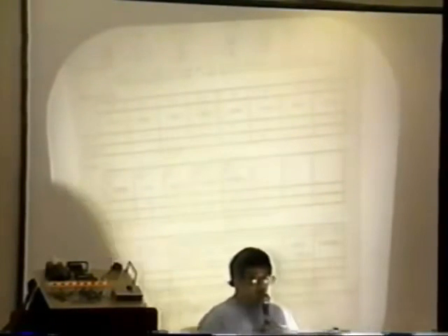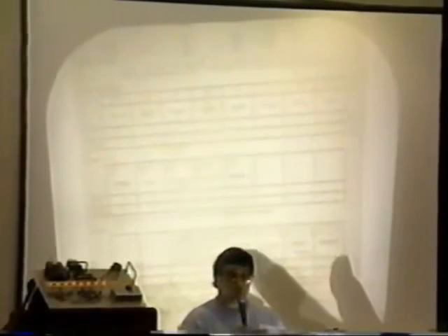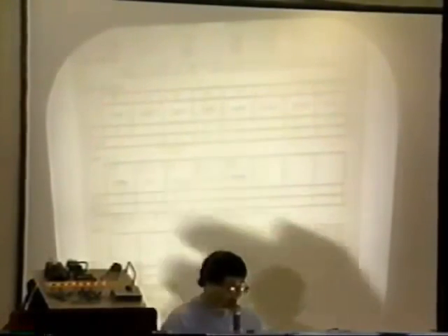So what I said was, let's take these top 4 and these low 4, we read them in, and use a logic instruction called OR, O-R, bring them together, these 4 and these 4, let's see, 4 and 4, that's 8. I got a byte of information from these 4 and these 4. Guess what? I got a byte coming in, and I got 8 control lines going out. I can rule the world with that parallel port.